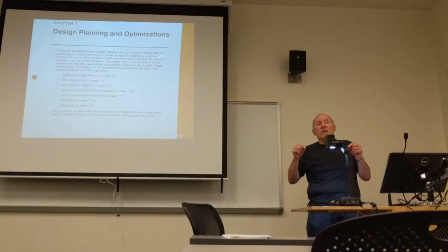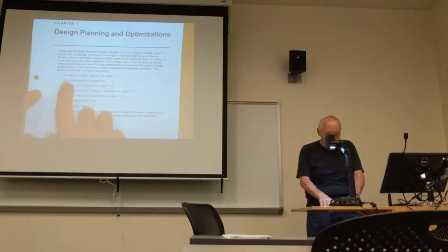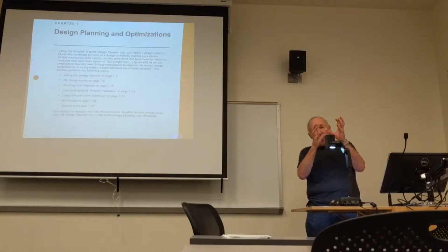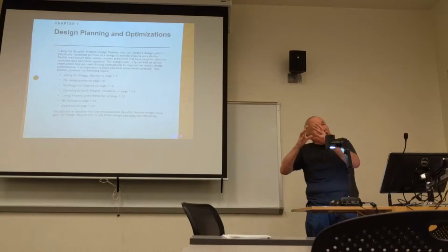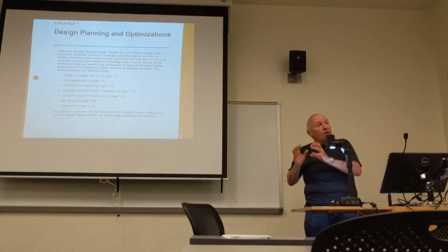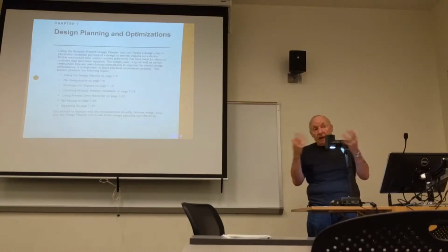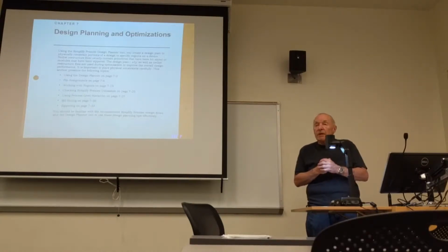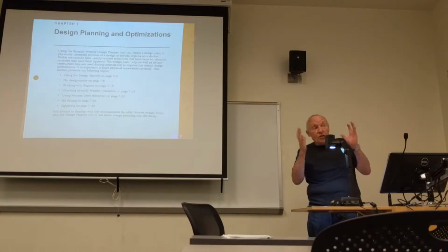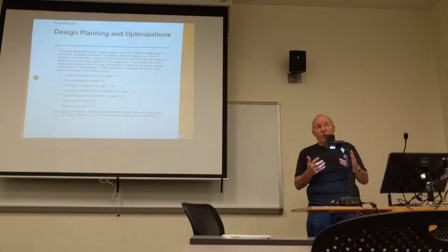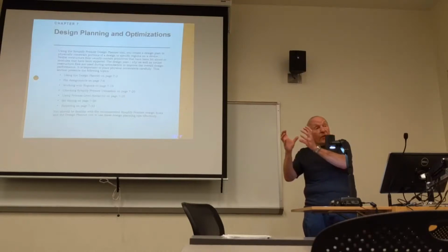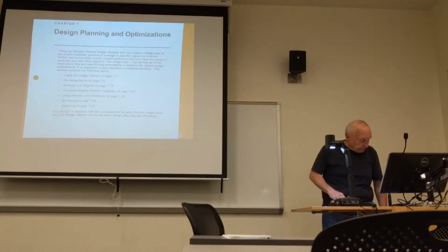So one of the things that you are able to do through some of these tools like Design Planner is actually move something around inside the FPGA. So it's still implemented the same way, it's just implemented in a different subsection of the FPGA fabric, and that can lead to improved timing. So in some cases, there's nothing wrong with your design. This is a placement and route issue where you need to move things around on the FPGA fabric to achieve better timing.